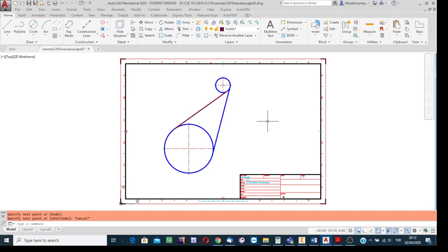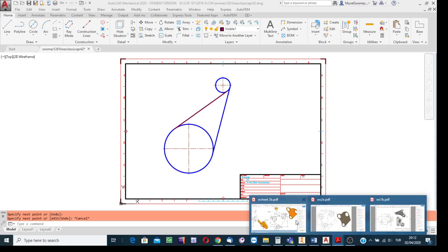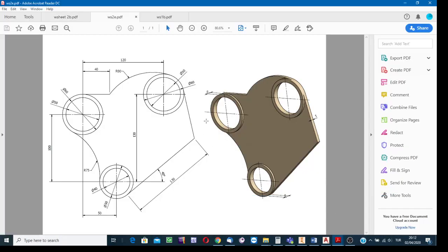This case is not so difficult to deal with. The only trick is to start the line drawing process first and then set the snap configuration. Enable the software for tangent points only. How about the other case? It is the most difficult case to deal with.